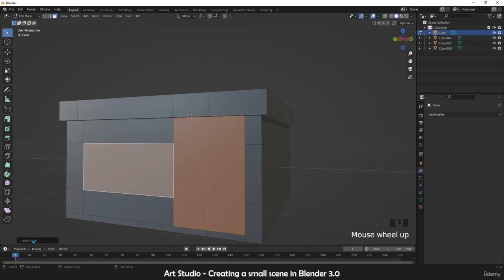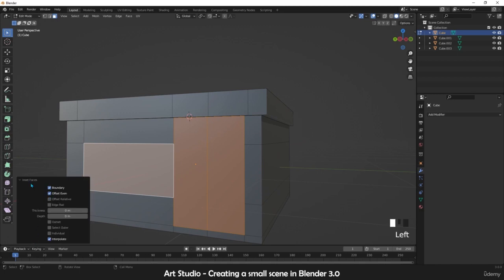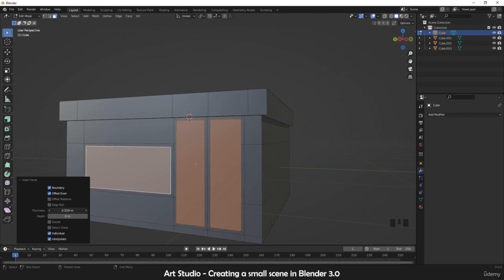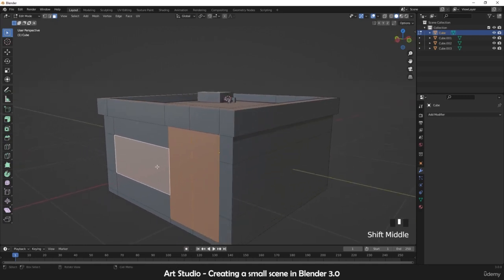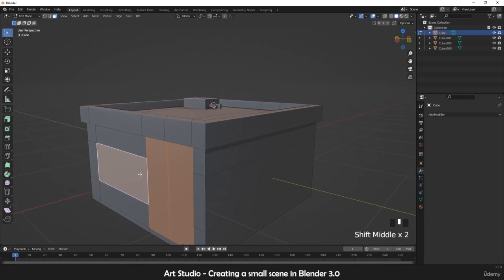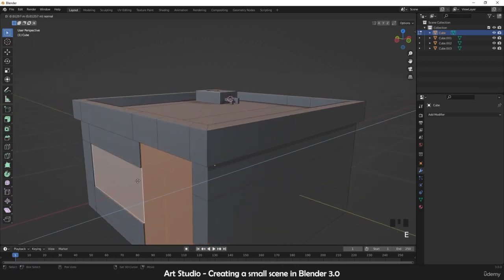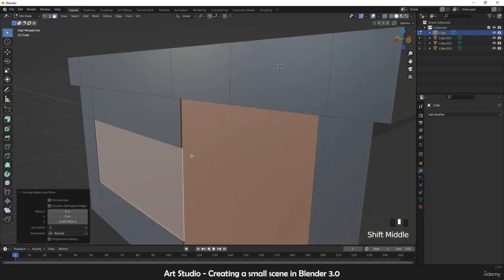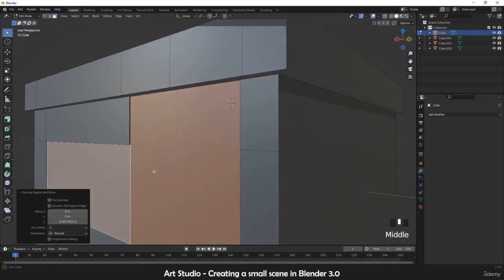And you're going to see a small icon, or maybe a menu that pops up here. So select individual and thickness. Make that thick. Give that some thickness, okay? Or maybe, let me first select that, okay? And press E to extrude that inside just a bit.